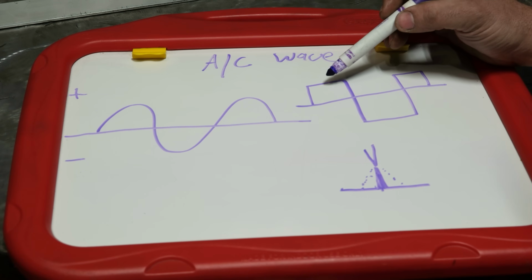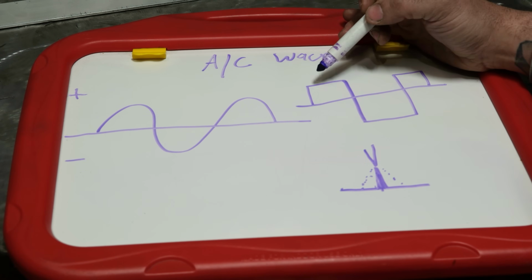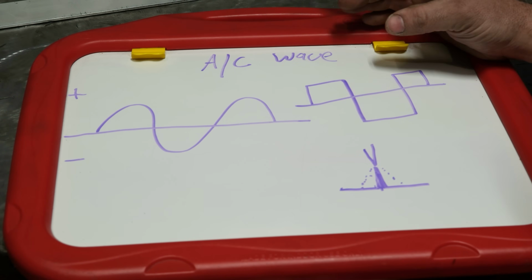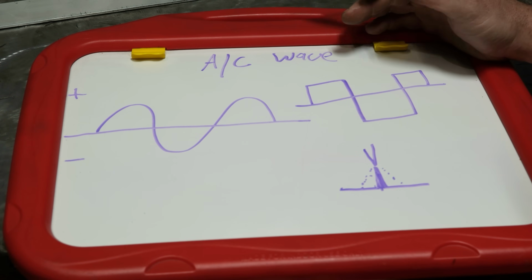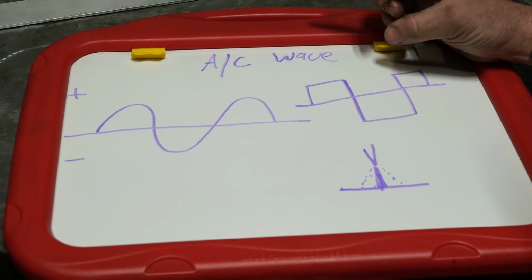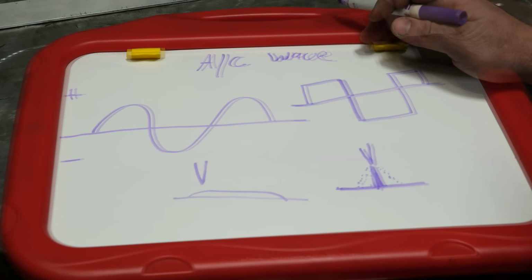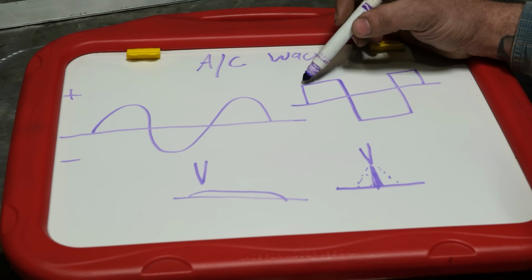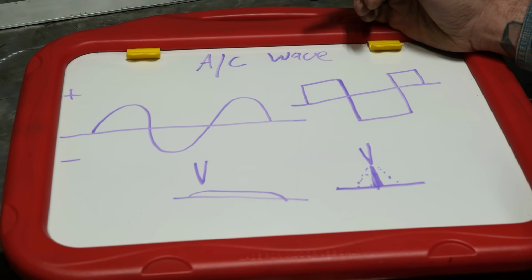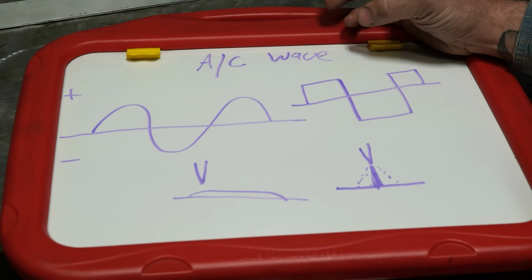The benefit of having an AC TIG welder that can do square wave is it affects how liquid the molten puddle is. So on pure sine wave, it tends to produce a more liquid, flowing out weld. Now with square wave, where you have a fast, abrupt change from positive to negative, it tends to make a less liquid weld pool in my experience.